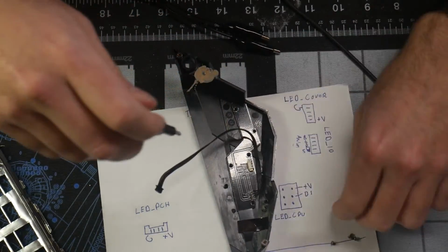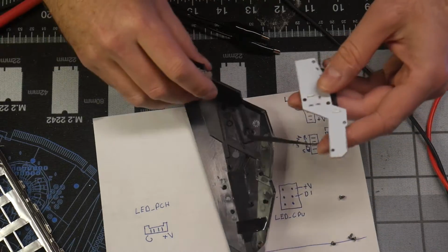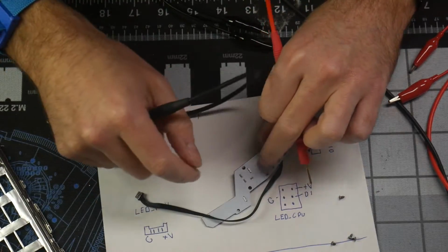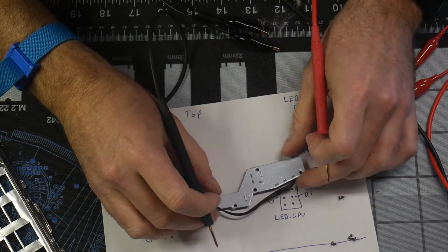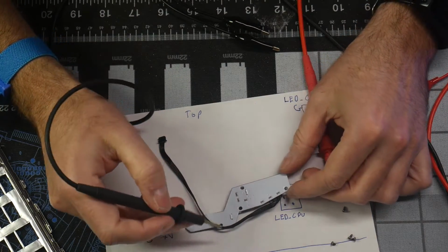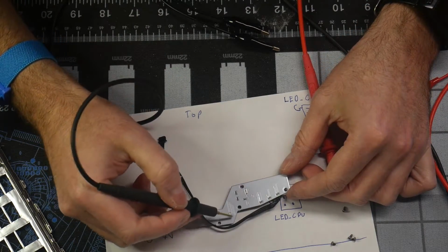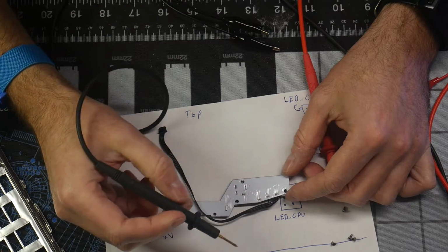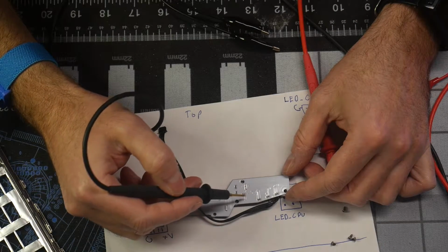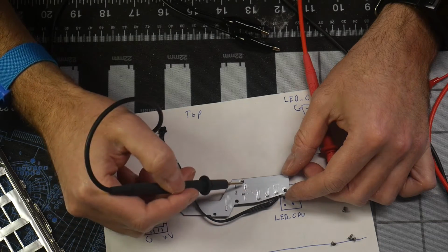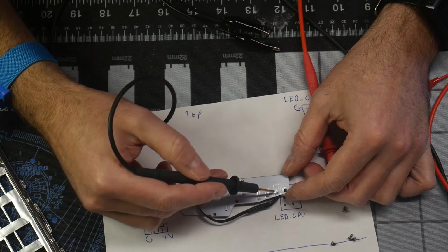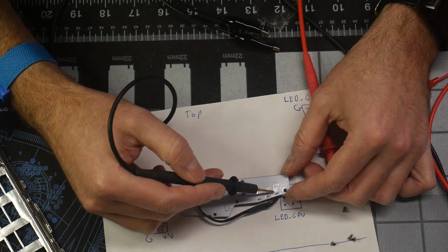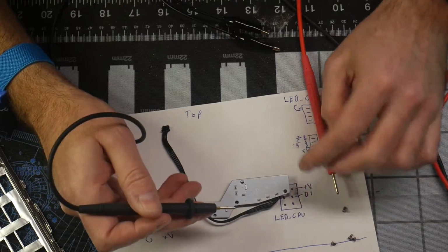Again, this is not really a standard, because they can change between motherboard revisions and whatnot. But looking at these LEDs, I see there are 2 LEDs right here. They're connected, and I also see that there are 6 resistors. Since there are 2 LEDs and 6 resistors, that means we have 1 resistor for each color, and each one of these resistors is for red, green, and blue.